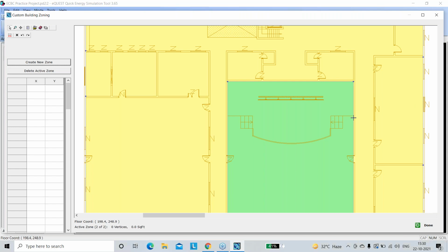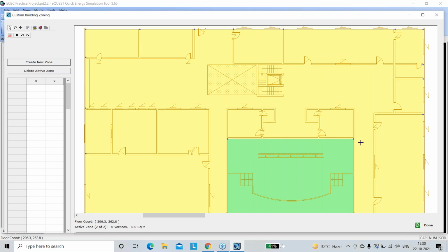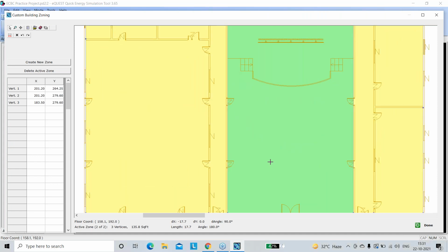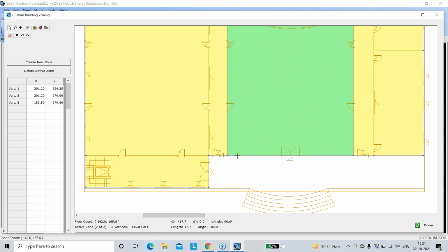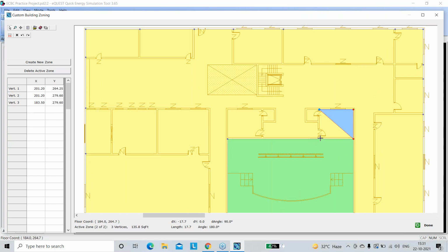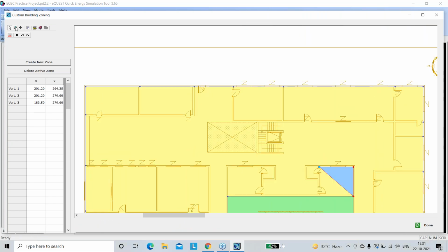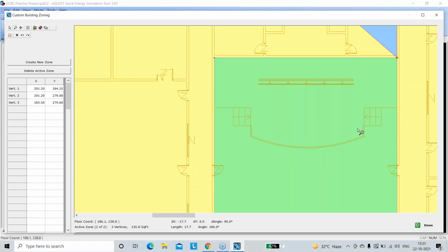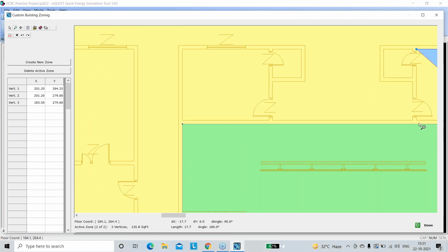Okay, just for the sake of time, I'll just go forward again like this. We create one here. Now see here, what I did wrong is I created one vertex here, I created one vertex here, but I did not create a vertex here or here, right?